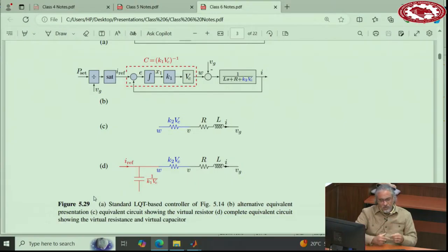This also stores electrical, electrostatic energy. So when it is working, it has some energy stored in it. And then when this voltage suddenly drops, let's say because one load switches in, this voltage tends to go down, and the whole voltage across this line tends to go down. So the capacitor releases energy.